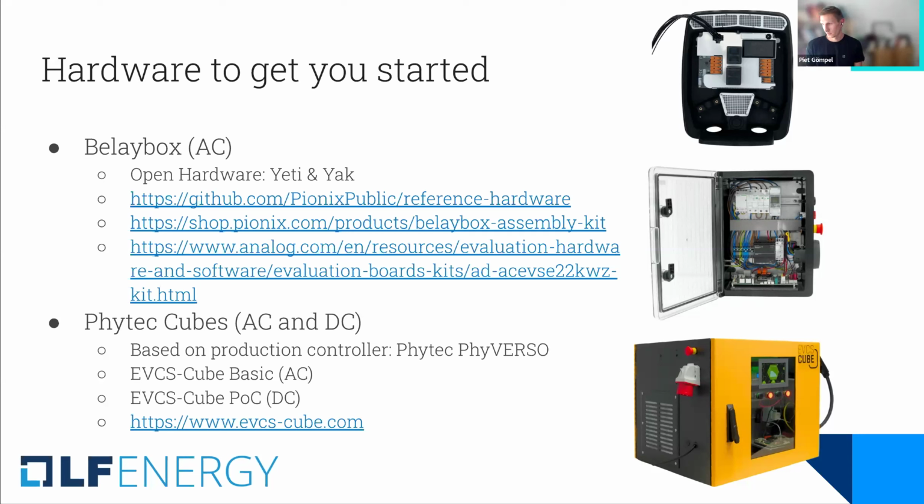So authorized remote TX requests is a configuration parameter in OCPP to specify if remote starts should be authorized by the CSMS. If this is set to true, I mean, it's a very specific question, but the libOCPP just calls the provided token callback that publishes this token, and the libOCPP consumer is responsible for checking the argument of the provided token callback and check if it's pre-validated or not, because in case authorized remote start transaction request is set to false, we don't need to authorize this token, it's validated already.